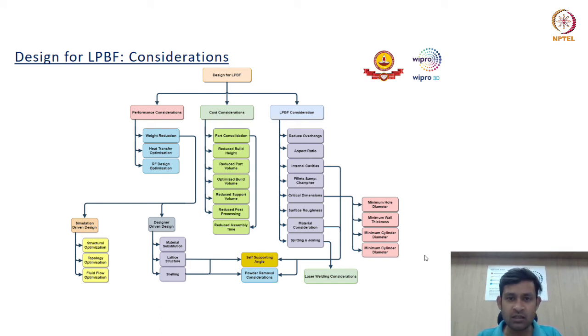So if I'm making a channel or a hollow structure or a lattice structure, I need to figure out a way to pull powder out. So this is an example of LPBF consideration.